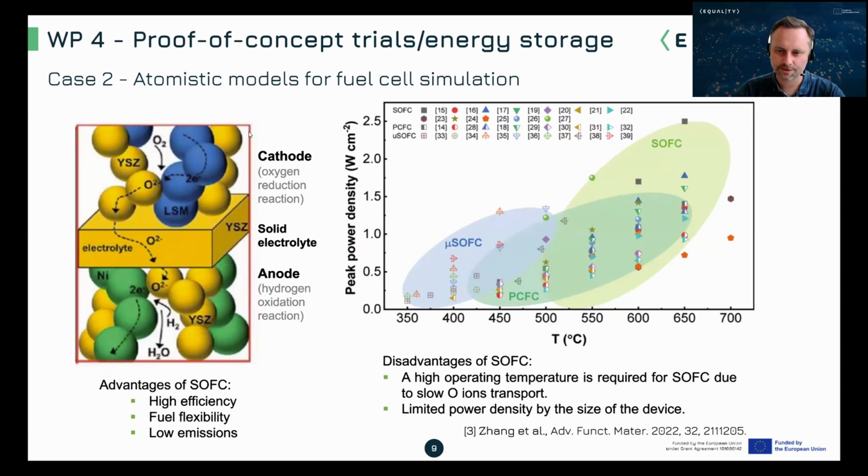These cathode, anode and electrolyte in between are all solids, while the cathode and the anode are not completely filled. They are like a sintered material composed of complicated ceramic materials that are necessary for transporting the oxygen ions and also the electrons. On the anode side, there is the same basic material as on the cathode, but it's mixed with nickel.